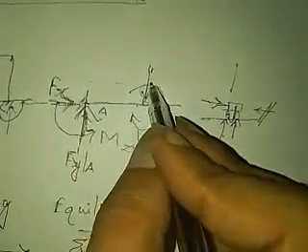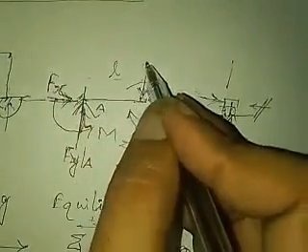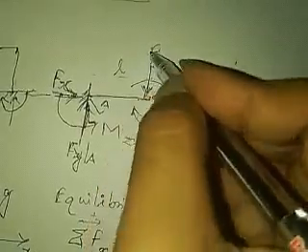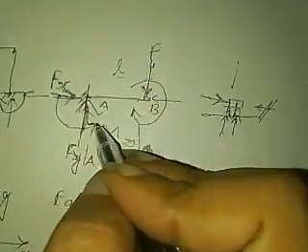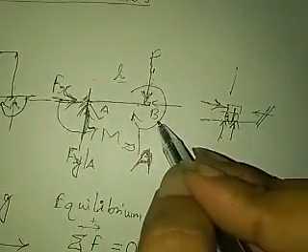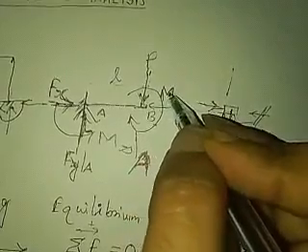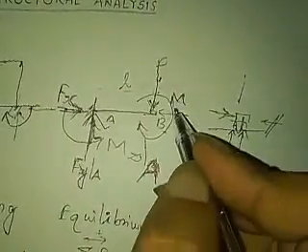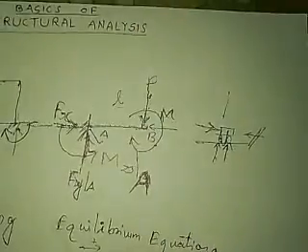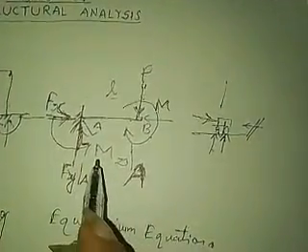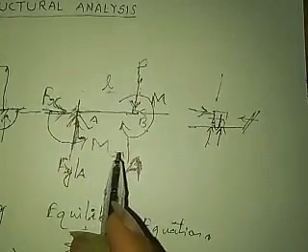You can say this is length L, and this load is P, then P times L will be a moment. Even when the moment M is not present, then M plus PL will be the combined moment which will be offered in reaction by the support, which will be equal to mz.